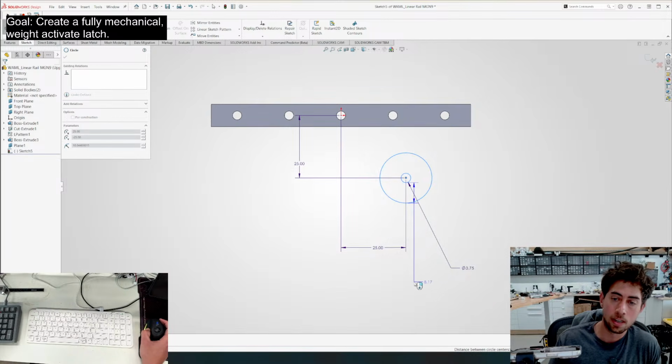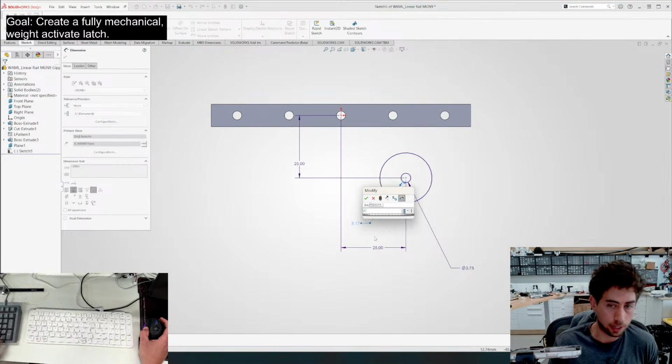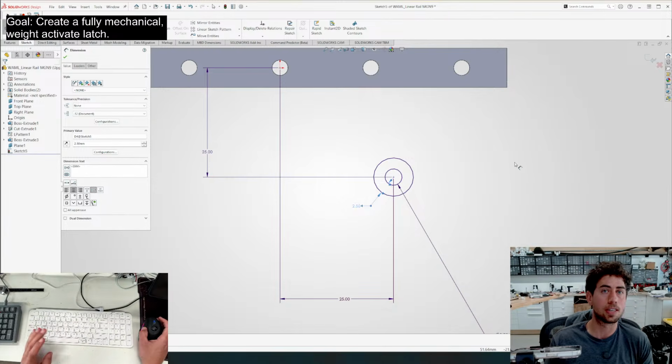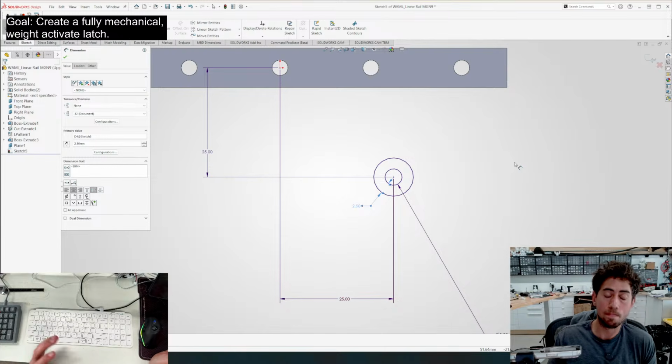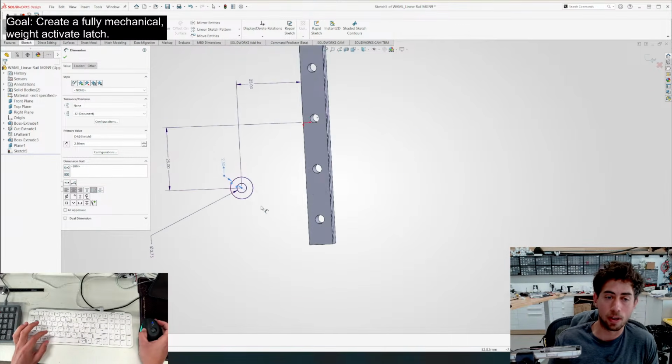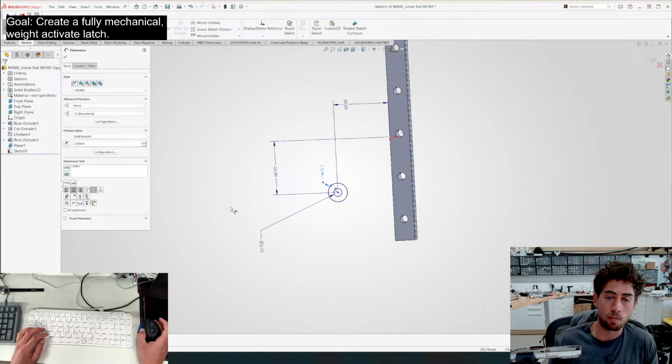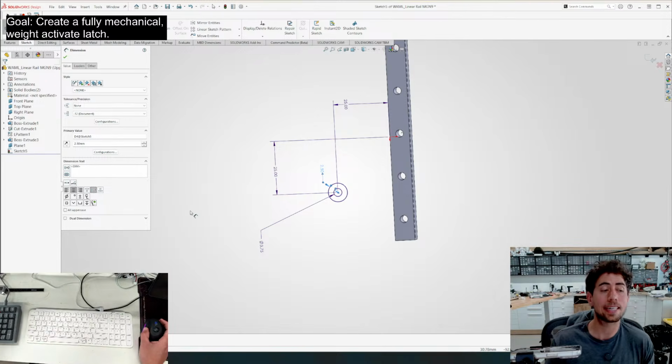And I think there's two reasons for that. One, obviously I've just done this a lot, but two, using fixed dimensions makes the decision-making process a lot easier. Like a million times easier. So that's the main reason. A lot of times I'll use 2.5 for a wall thickness. And we're gonna get to how that prints on a 3D printer. We're gonna get to all of that.